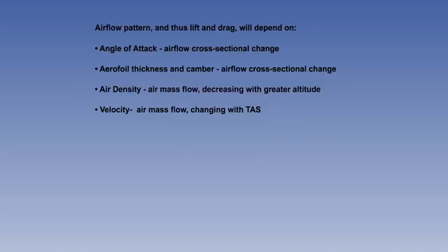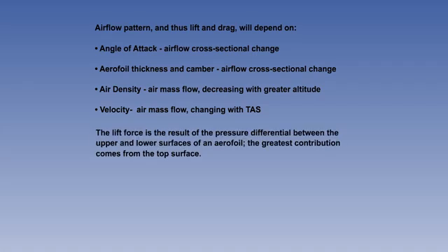To summarise the significant points of this lesson, we can start with the main things affecting airflow pattern, and consequently lift and drag. It will depend on angle of attack, airflow cross-sectional area change, aerofoil shape, that is, thickness and camber, again airflow cross-section, air density, air mass flow decreasing with greater altitude, and velocity, air mass flow, changing with TAS. The lift force is the result of the pressure differential between the upper and lower surfaces of an aerofoil.